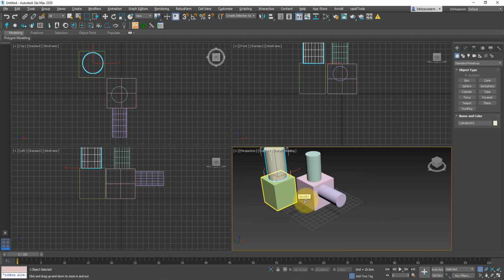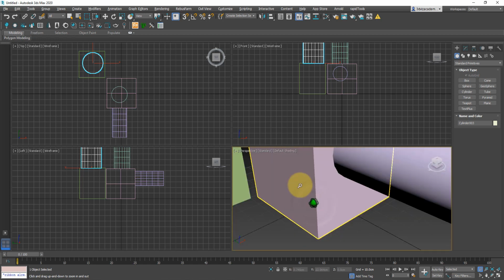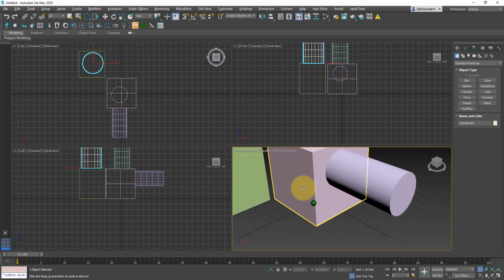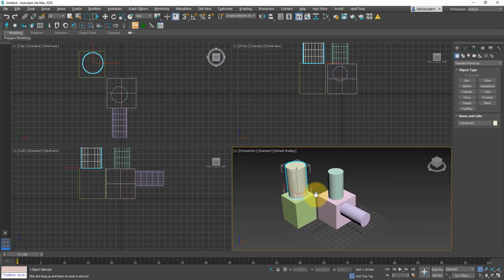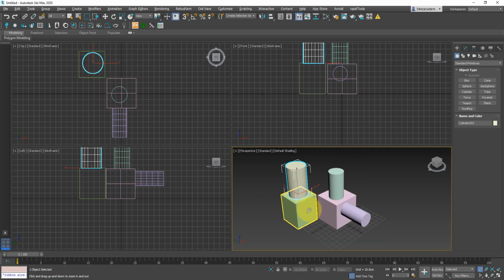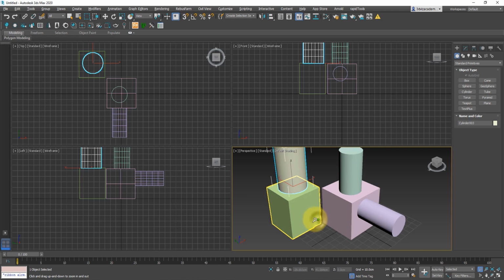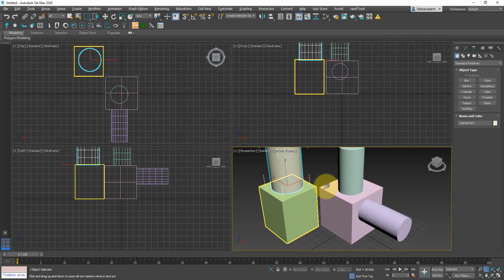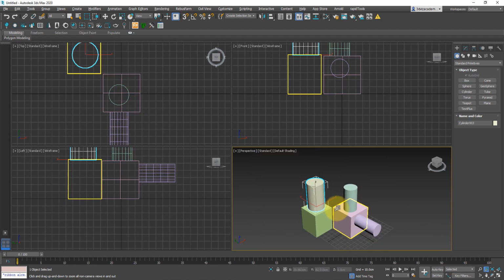But if you want to have a little bit more manual control, you can pretty much do it with left mouse button. This is going to be pretty much the same as your scroll, but scroll has this tendency to jump, while zoom is going to be a little bit smoother. Now, the next thing we got on our list is zoom all. This is going to work on all of your viewports at the same time. Pretty handy when modeling from blueprints and you just want to keep your scale.